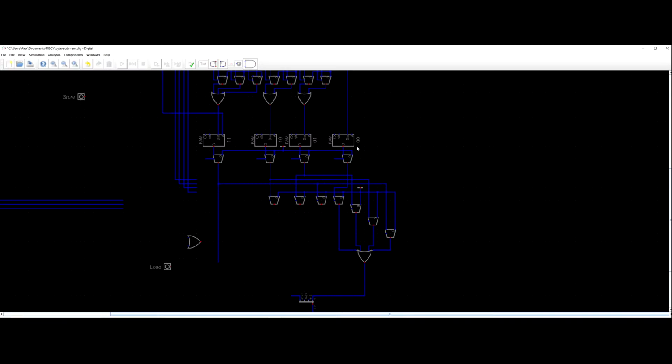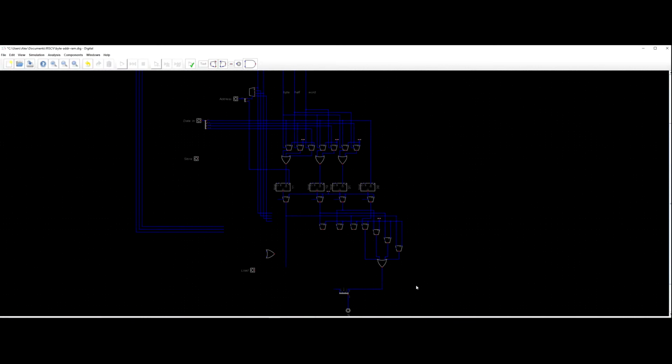You could generate a half word from this one, and the low word would come onto there, or a half from here, and the low word would come onto there. Or you could read the full word out, and it comes onto there, right? So I need several ways of controlling this. So I need like an OR gate on each one of these mux inputs here, which just blows up the complexity of that.